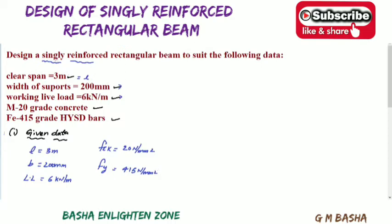Already in the question itself, they will clearly mention that it is a singly reinforced beam. Generally the question will come like this: design a rectangular beam to suit the following data. They didn't mention whether it comes under singly or doubly. Based on the conditions, you find out all the moments, and see whether it comes under Mu less than Mu limit or Mu greater than Mu limit.